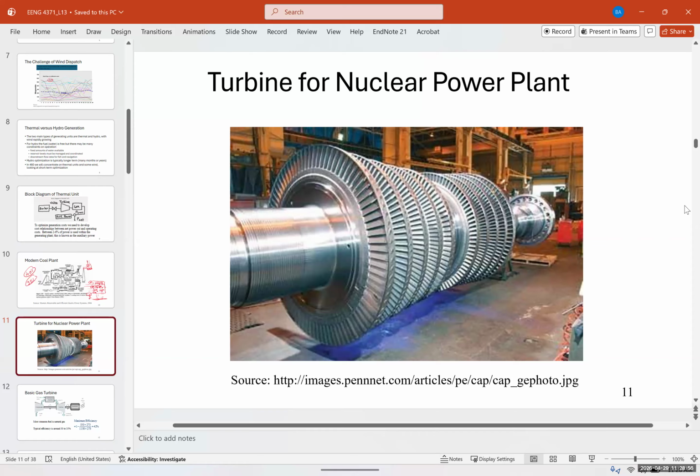Nuclear plants are baseload units. They are very expensive to build, but the fuel cost is relatively low. They run best at constant full power output around the clock, given their large physical size and long startup times. It requires days to bring a nuclear unit from cold shutdown to full power. They are almost never used to follow load variation because it takes days to turn on and turn off.